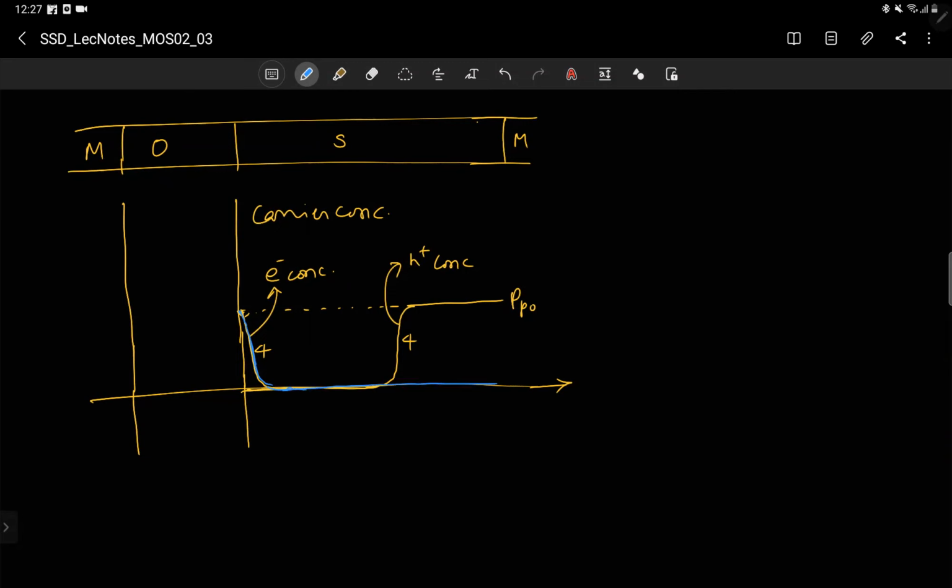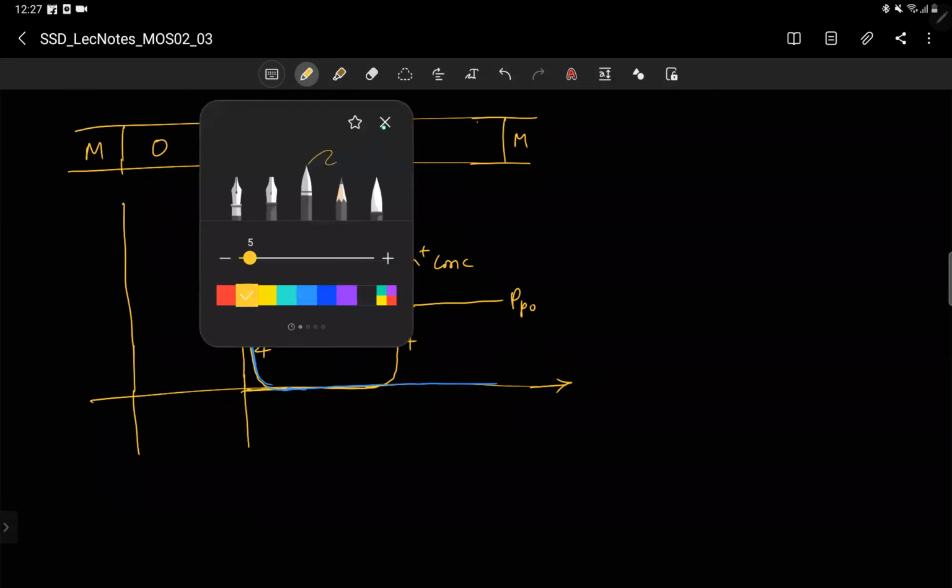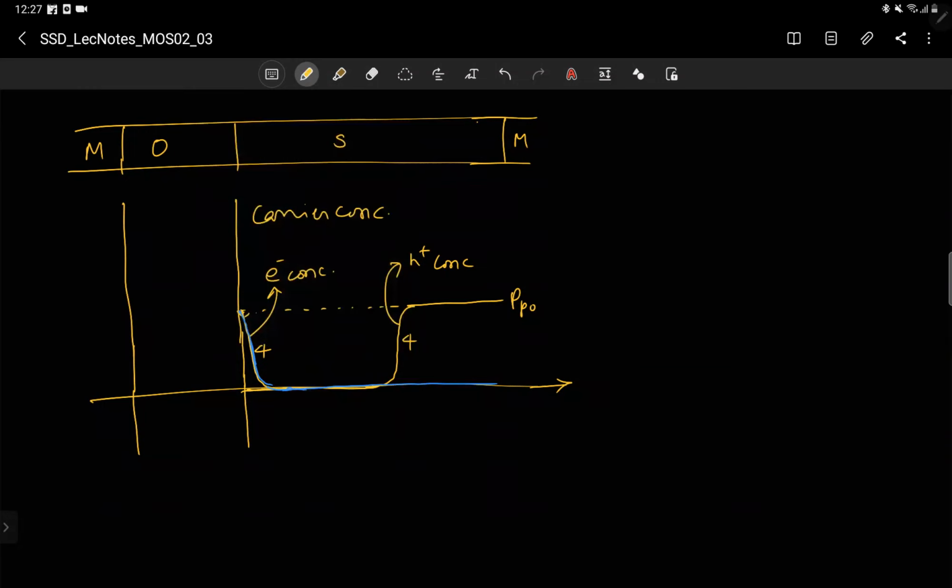Okay, so we are interested in this VT. For this picture, let us calculate the applied bias. It is like reverse working. We know that this is the threshold voltage, and this is how the charge profile looks. If you find the potential drop, that should be the voltage that we should apply. So it is like working the reverse way.